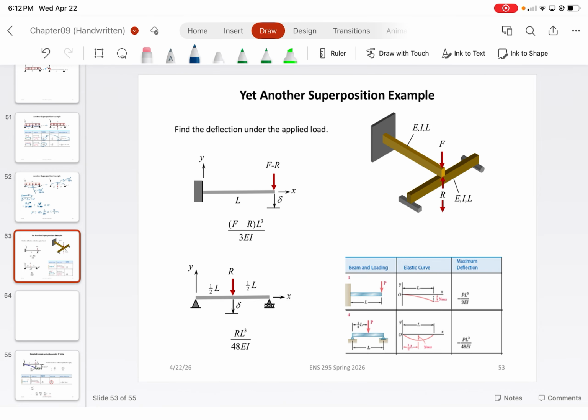The reason for the R is that the R force is basically being transferred. It's a transfer mechanism, so the stiffnesses are shared between the two systems. They're two separate systems where the load being transferred between the cantilever beam and the simply supported beam is split in some way, and it requires some knowledge of how the loads are transferred.